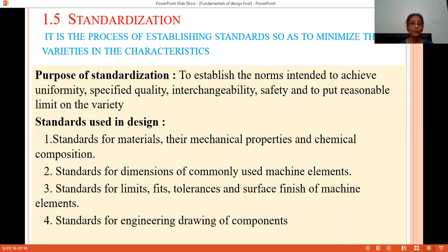Standards for chemical compositions. Chemical composition means what? How much is the alloying element? For example, we have seen a designation of the material. First is a figure 100 times the average percentage of carbon, followed by the chemical symbol of each element, like in a commercial designation of material. So these are standards for material which will be accepted, and those standards will vary.